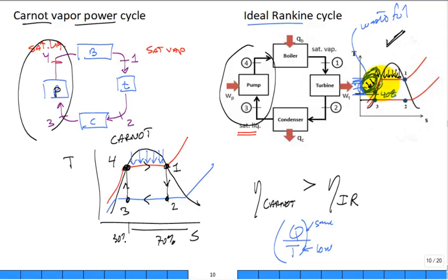Where does that entropy have to go? Oh, you can destroy entropy. Can you destroy entropy? Nope. It can only get more of it, and you don't want it. You're going to have to dispose of the entropy. You have to push it out of the system. Where are you going to dump it? You have to only dump it in the condenser. So entropy is going out down here with that heat transfer, and you're dumping out that entropy. It's like a waste product.